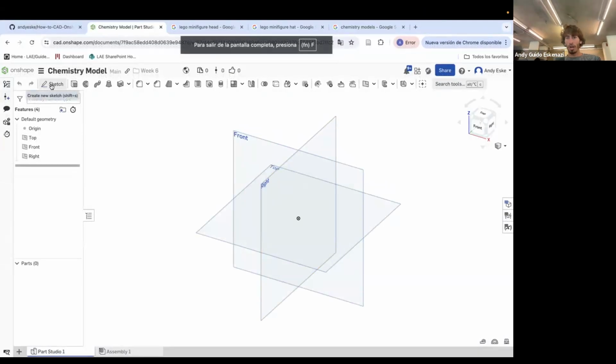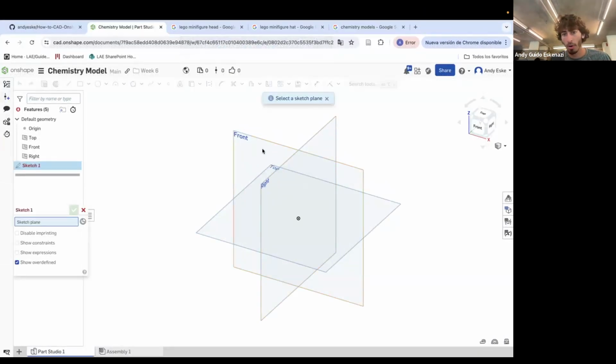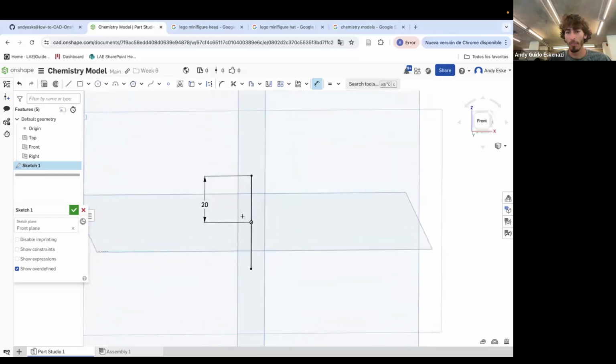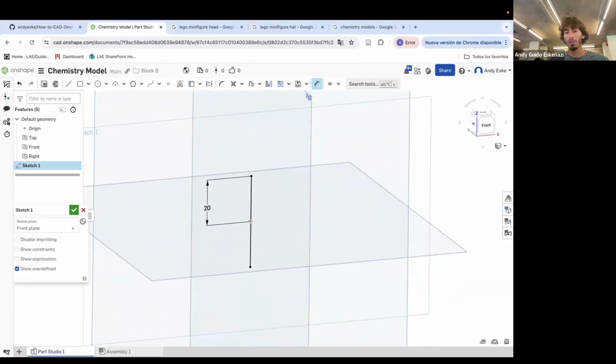What I would start doing now is I will click in Sketch and go over to front. It's an interesting warm-up exercise because then I can just do a line, and we're gonna do a half circle on that line and then do a revolve. But before we do that, let's do a line that goes like this, that way, and then I click on letter E and I'll make these two equal. The dimensions don't matter in here. So then this is a square pattern, which means there's gonna be bonds coming off in this direction, that direction, that direction, that direction, and then on the other one.